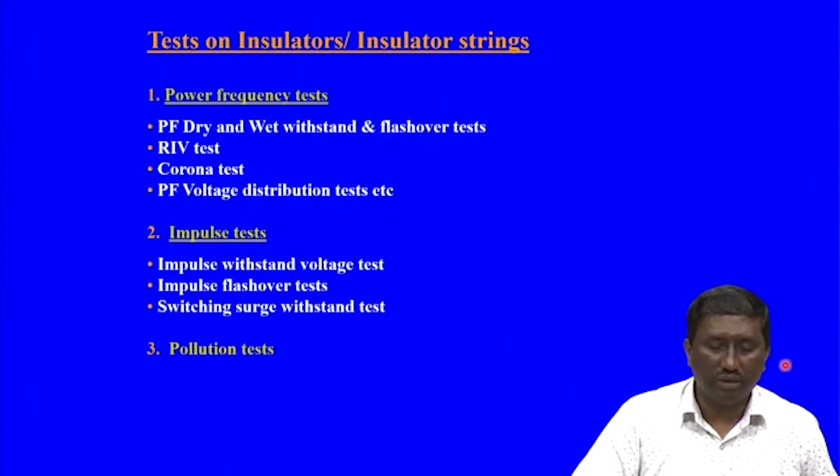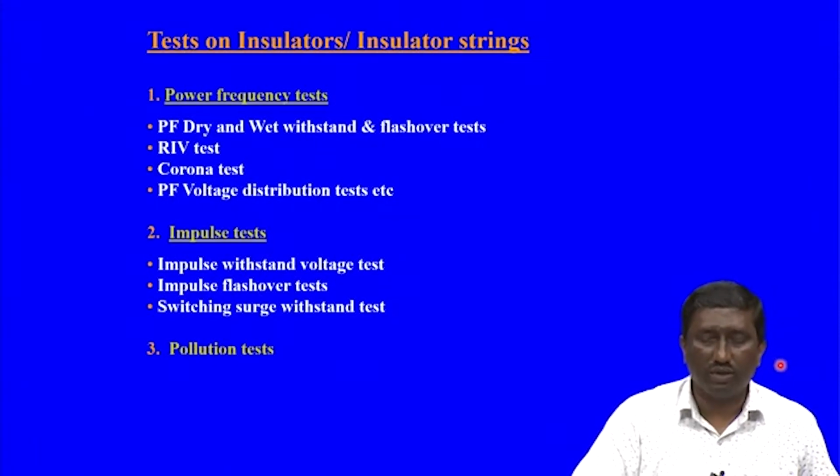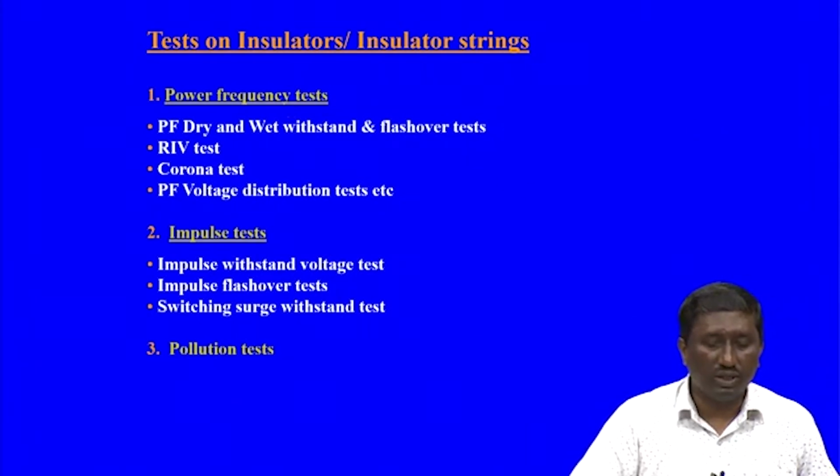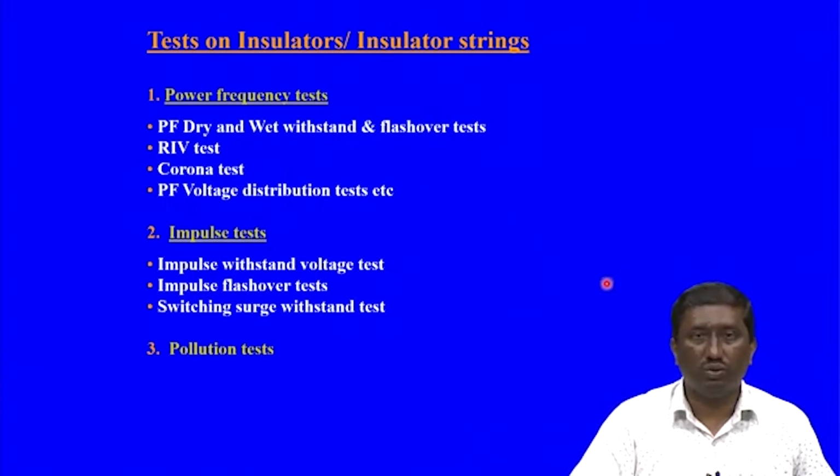So, various type tests as per the international standards are being specified for different equipments which are used in high voltage and extra and ultra high voltage range. Some of the tests include power frequency tests, where these are operated at 50 hertz. The power frequency dry, because for clean conditions, and wet, that is because of the rain which the equipment could see in service. So, this dry and wet conditions have to be simulated in the laboratory, and the power frequency dry and wet withstand test and flashover.